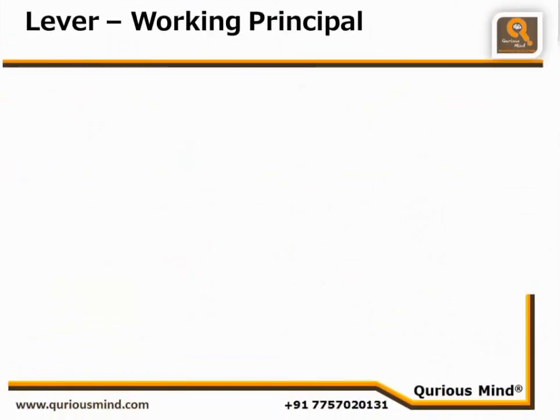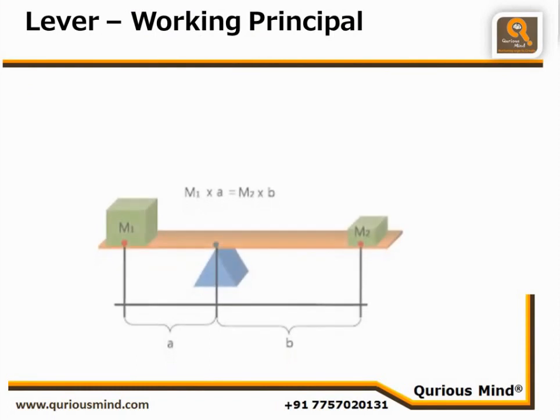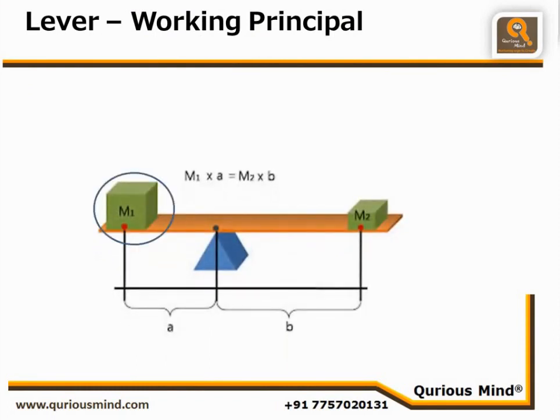Lever is not a component but is a concept. Many parts can be used as lever. Let's assume that M1 load is placed on one side of the lever and M2 load is kept on the other side. Now to balance the load over the lever, the fulcrum point needs to be placed such that the product of the load and the distance between load and fulcrum point is equal on both the sides.